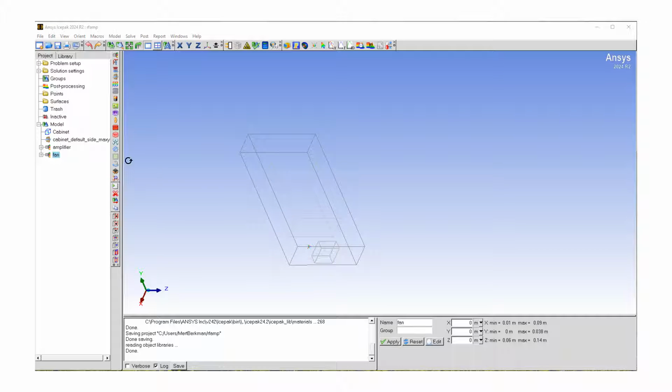So let's start talking more about meshing. One of the concepts in Icepak meshing is called slack. This is essentially a small additional marginal distance from your object, which you specify so that the passage between non-conformal cells is smoother.